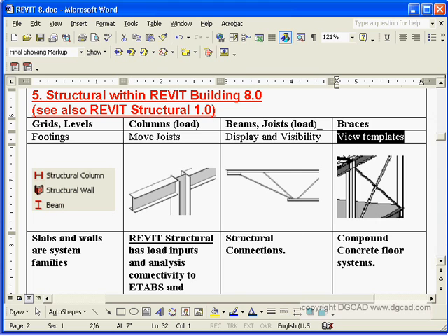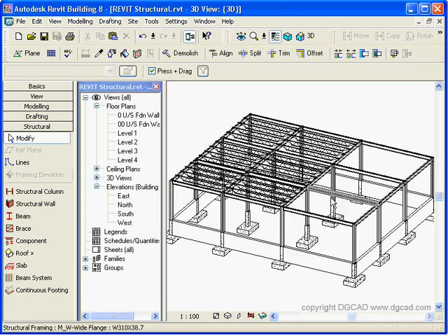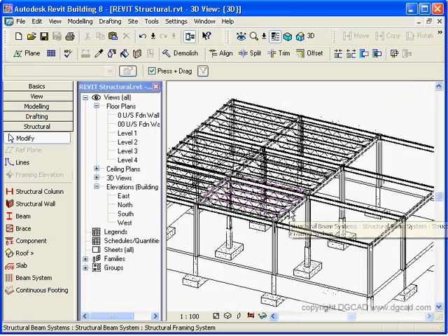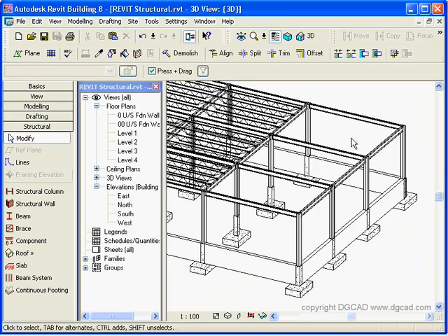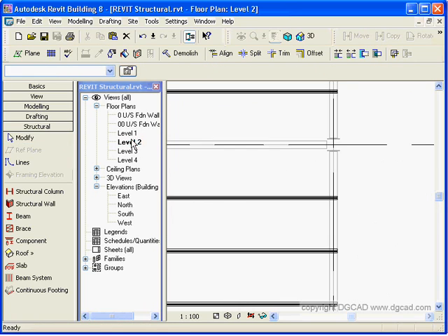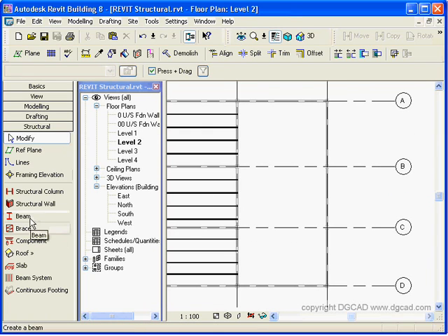So I'm just going to switch over to my Revit, and I'm looking at my underside of foundation wall plan right now. So that's what we've got so far, and again there's our different beam systems that we have, and you can see it highlights it in green. You can go in and edit, and I pulled those over, and I could probably make those joists deeper. So just to finish that off, maybe I'm going to click here and click here, and then I'll delete those, and I can go back to say my second floor level and zoom out, and now I can go in and maybe put another beam system in there.